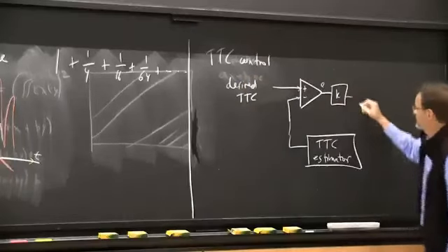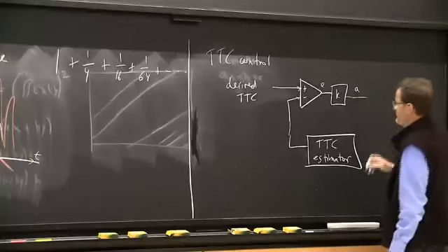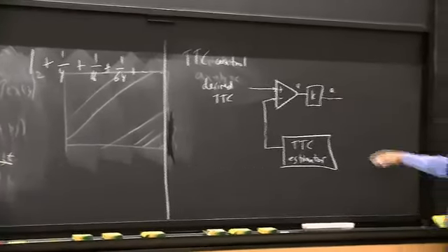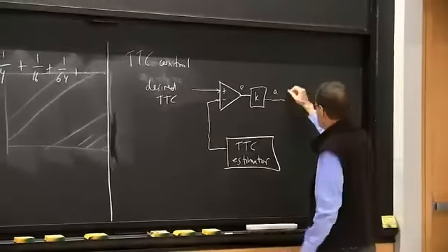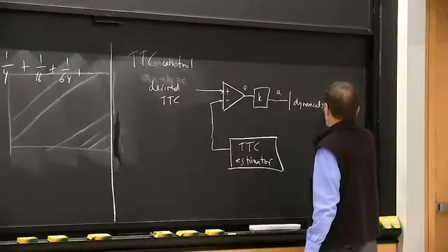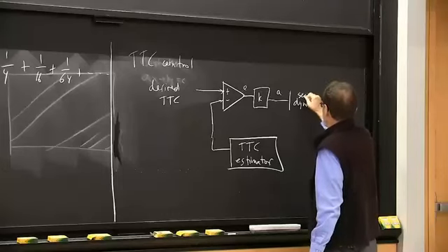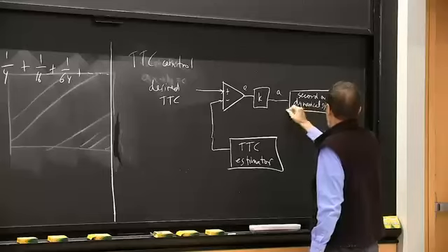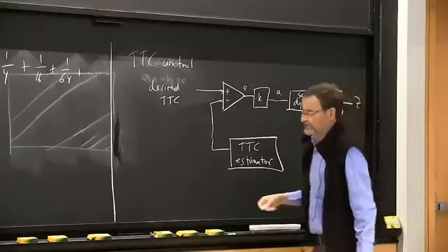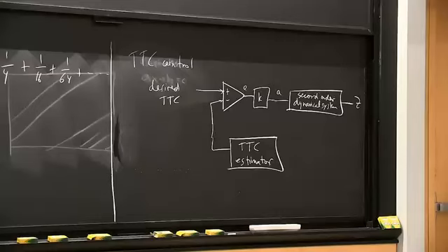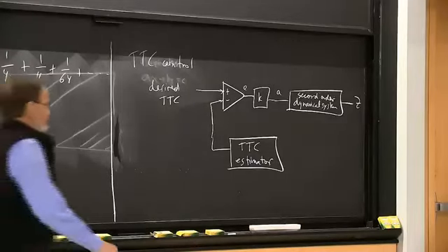And we multiply that by a gain, and we use that to control the rocket engine to change the acceleration. And then there's a dynamical system, which is second order in the sense that we're controlling acceleration, not height directly. Height is two integrals down from the part that we can control.